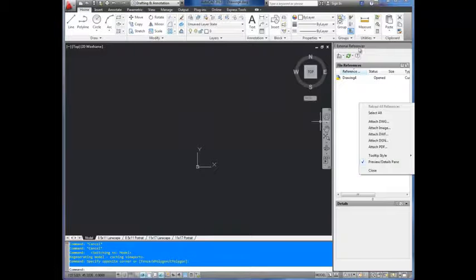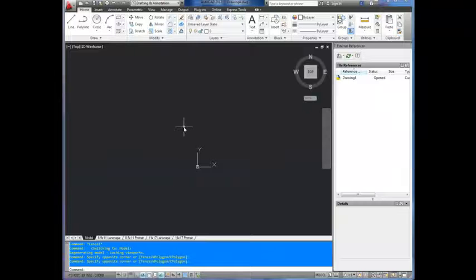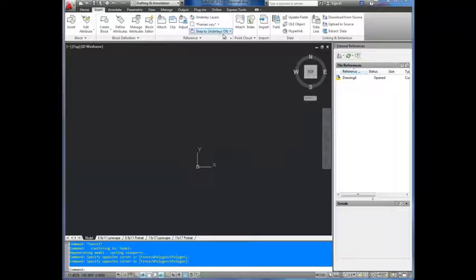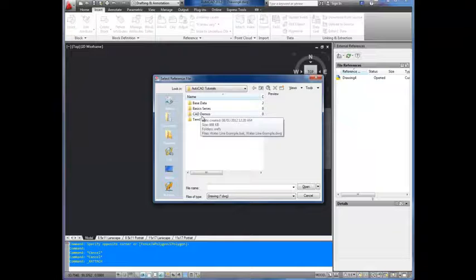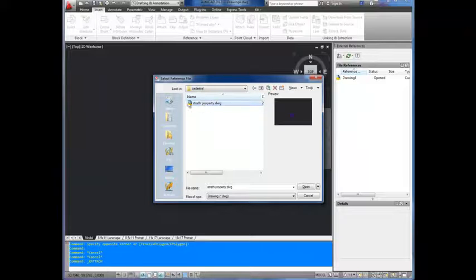We're going to go to our external reference, and if you don't know how to use those, I did a video on that. You can check on my channel. It's how to use XREFs, or external references. To bring this menu up, simply go to the Insert tab and click this arrow here. So over here, we're going to right click and click Attach Drawing. We're going to go to my base data folder, wherever you've saved your stuff. There we go. And the street was Strathcona.